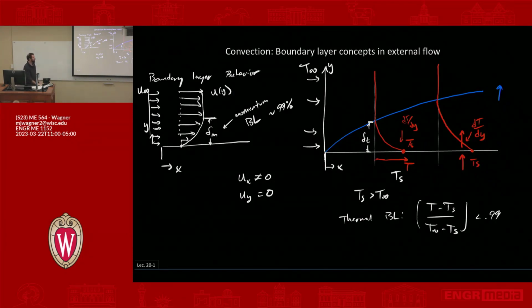We'll talk about this more, but at some point you're going to get such a shallow gradient of velocity with respect to y that the shear stress becomes really small, it becomes unstable, and you get turbulent flow. So eventually the flow will transition to turbulent. But if it was prevented from doing that, that boundary layer would continue to grow indefinitely.